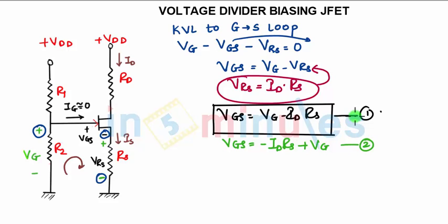Now we can say these two equations are one and the same, just the way of writing is different. Both are for a straight line with decreasing slope, but the origin is now not a point on the line. That means it is not starting from the origin, it has shifted to some point because of this plus Vg on the horizontal axis, so we need to find the points using the same equation. On the axes we have Vgs in volts and Id in milliamperes.